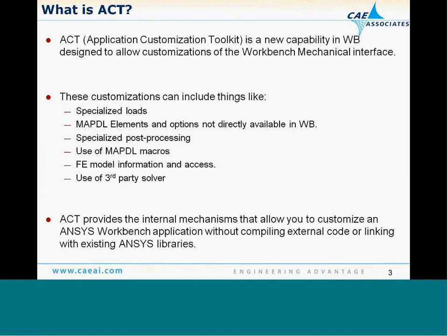But you can also use ACT for accessing information in the Mechanical interface, say node and element numbers, access to geometry, and different finite element information that you otherwise wouldn't be able to get to. And you can also use ACT to tie Workbench into a different solver. So those are the uses for ACT.